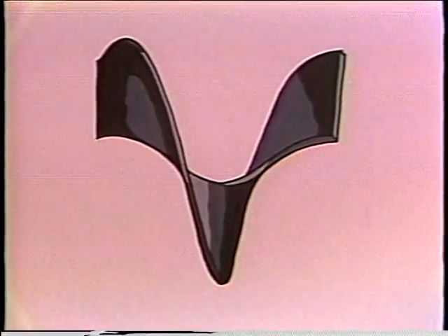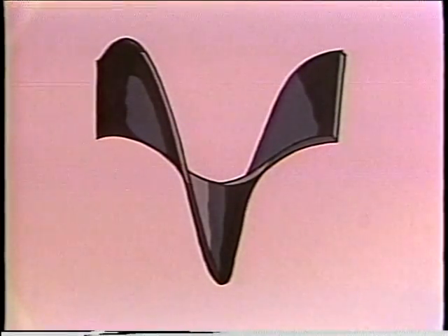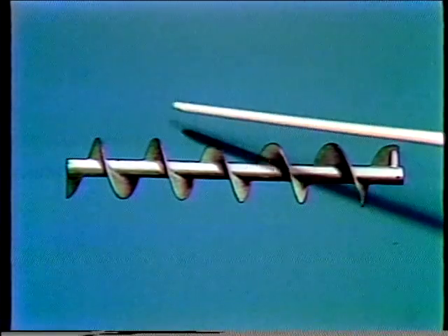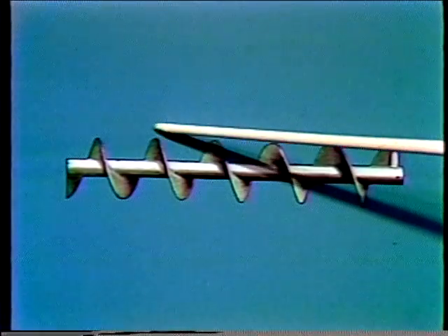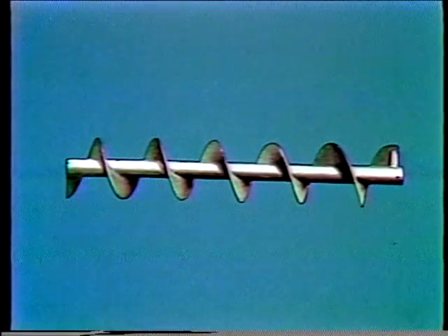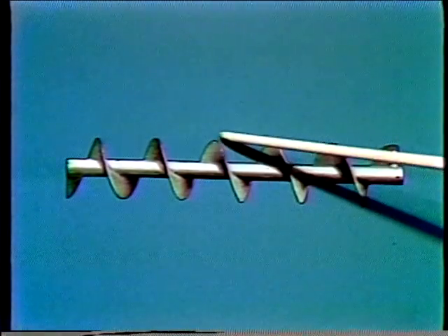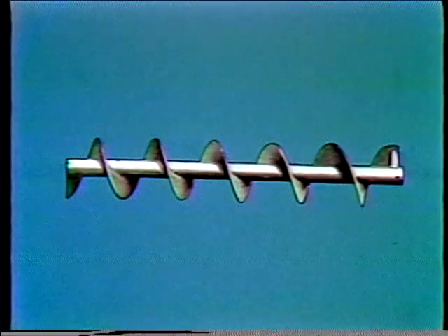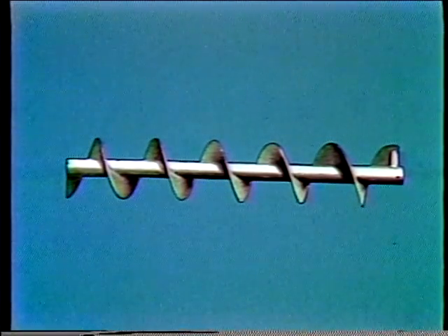The shaft is steel tubing. Various thicknesses of tubing are available. One pitch in conveyor is the distance from this point to this point. On standard screw conveyor flighting, the diameter of the screw is equal to one pitch. In other words, a 9-inch diameter conveyor would normally be a 9-inch pitch.